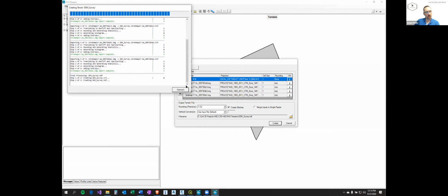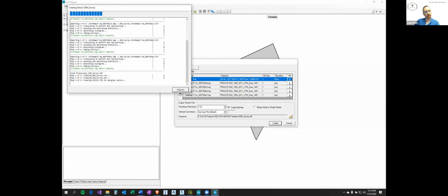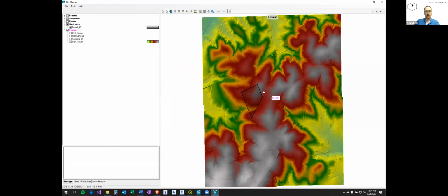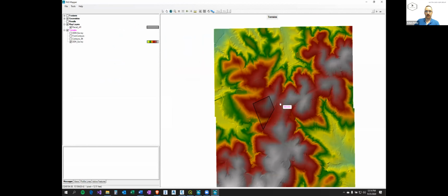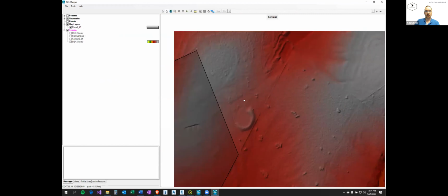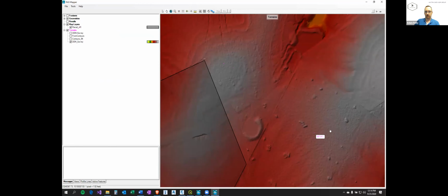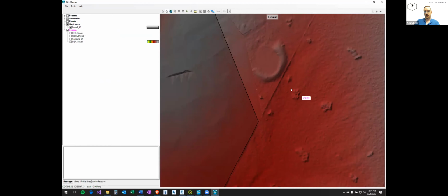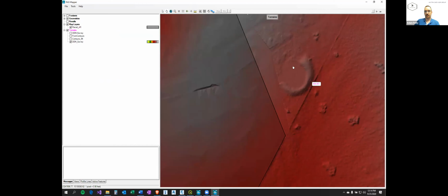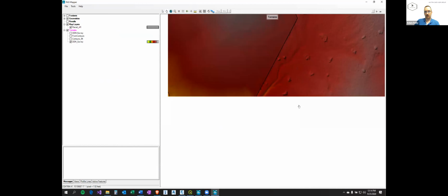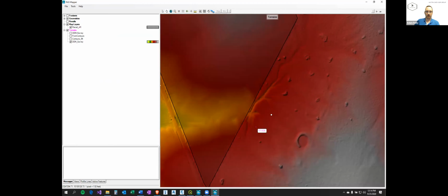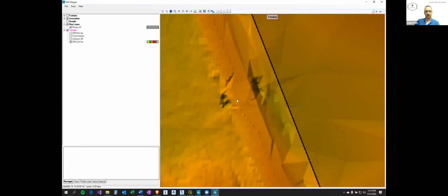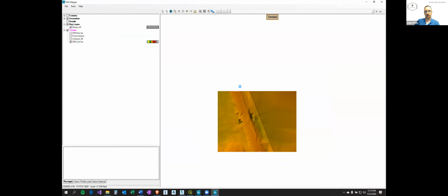Final steps, almost done. Okay, so now we have this much nicer looking surface. If we zoom in, we can see all this little bumpiness that indicates that there's more data than every 2 feet in elevation. We can see this little pond here. We can see this pond over here, some little hillocks, stuff like that. We can even see kind of where our culverts are as they cross this road that is now very visible in the model.